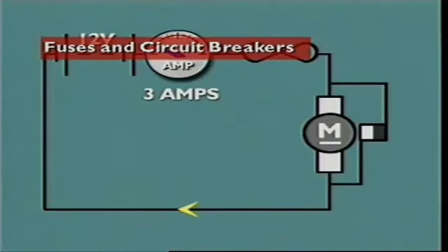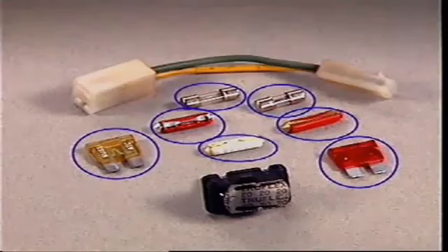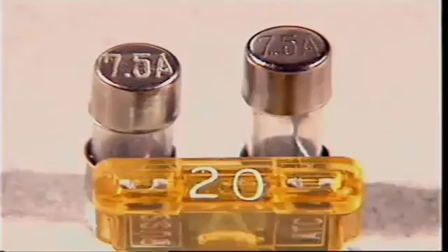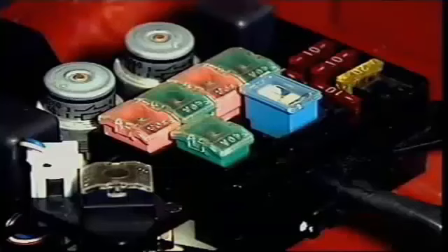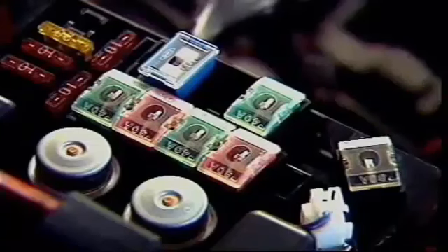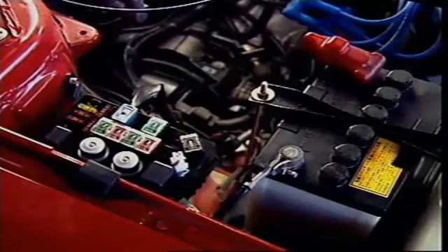This section examines fuses and circuit breakers. They are designed to break the circuit if current flow is excessive. The most common kinds are fuses, fusible links, and circuit breakers. They are all rated in amperes. Their ratings are usually marked on them. Fuses are typically used in lighting and accessory circuits, where current flow is usually moderate. A fusible link is typically placed near the battery and, except for the starter motor, it carries the current needed to power an individual circuit or a range of circuits.